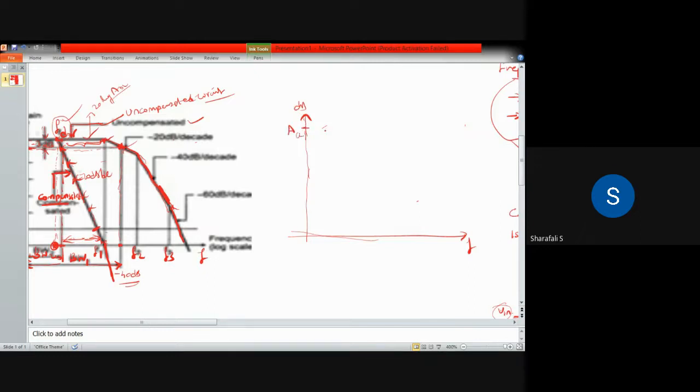And this is the closed loop gain in dB, against your frequency. Let's say this is your 0 dB. From here you have 10 dB, 40 dB, and so on for your gain. So your gain will be constant for some value up to that first break frequency.